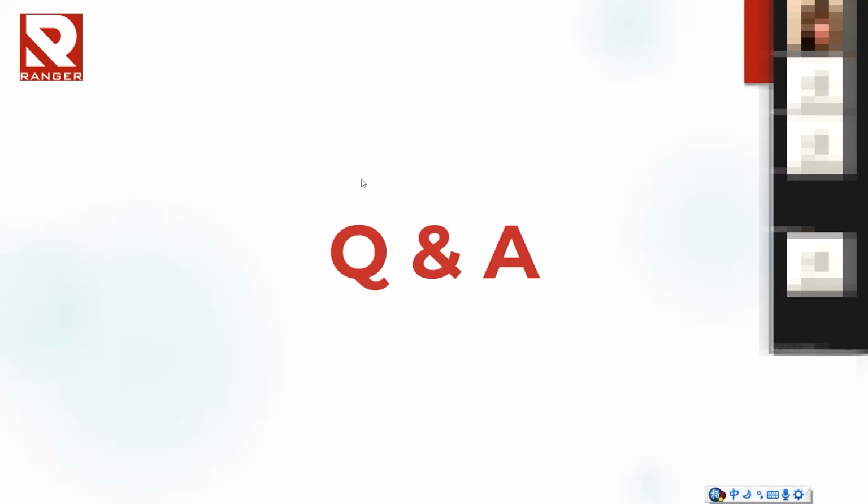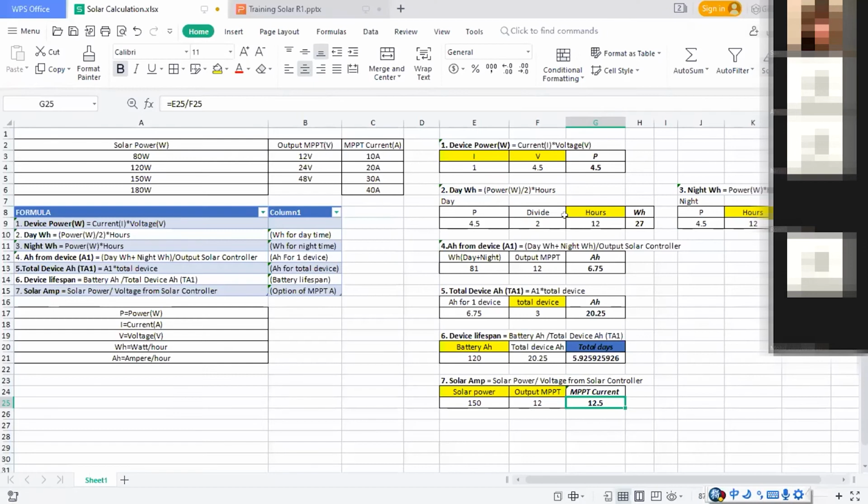Okay, why does day power need to be divided by 2? Because for the daytime, the camera will not use IR, so it will not use maximum power. So for the calculation, we just divide by 2 for the camera to calculate the power. So it must be divided by 2 for daytime. For nighttime, just times the 12, just times the hours of the nighttime.